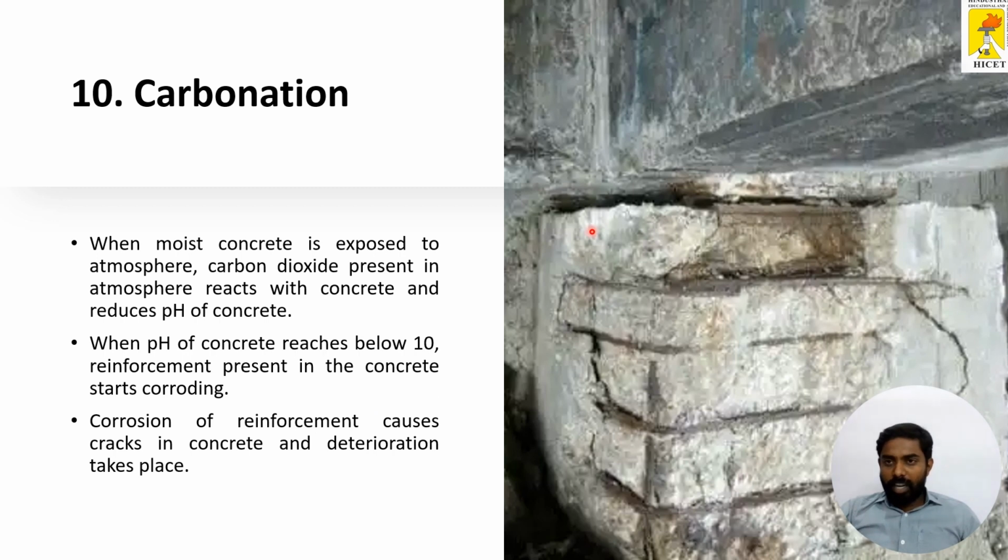Next one is carbonation. When moist concrete is exposed to the atmosphere, the carbon dioxide present in the atmosphere reacts with the concrete and reduces its pH. When the pH of the concrete reaches below 10, the reinforcement present in the concrete starts corroding, and the corrosion of the reinforcement causes cracks in the concrete and deterioration takes place.